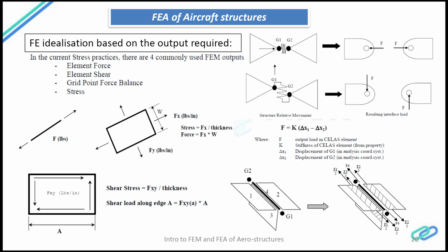So similarly, the equation for the spring element is this one. It is the difference between the displacements times the stiffness. And over here what I have put is the T section, which is the flange and the web intersection connection, whereas the flanges are modeled using 2D elements and the web is modeled using 2D elements, but the connection between them is modeled using a rod element. And these are the internal forces or the free body loads.